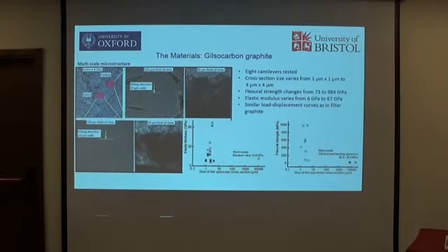So I did a similar test, microcantilevers from these type of regions with porosity. Again, the elastic modulus has a very large scatter, and it changed from about 20 all the way up to 60, 67. And the flexural strength has a high value of about 1 gigapascal, and the normal large samples have about 20 megapascal. So this tells us that for this type of sample, if we input this mechanical property into your modeling, this is really the data you need, and that's the data you output from your modeling.